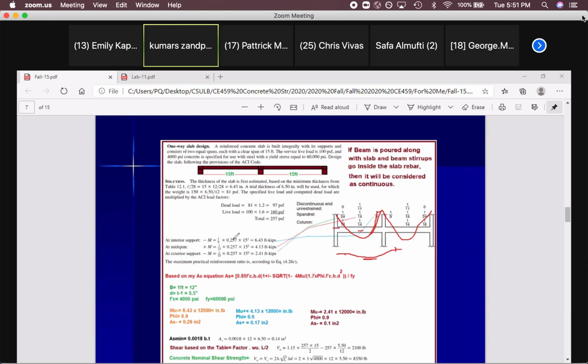Yes. Then in future, imagine you are a designer designing a reinforced concrete slab that has a huge load on top, so the percentage of the rebar is high. In that case, you can change 150 to a bigger number. Do you know what I mean? These numbers are just some guesses for the start. But if you have 4.5% rebar in your slab, it should be heavier than if you have 1% rebar.